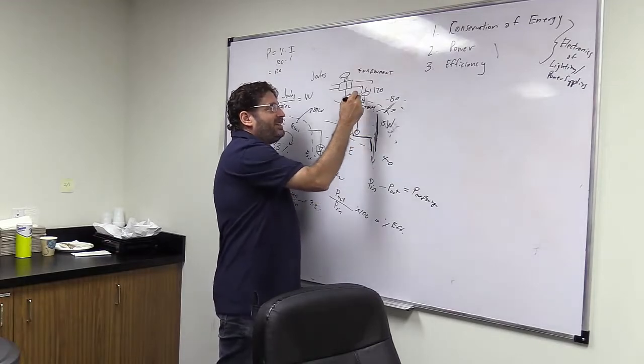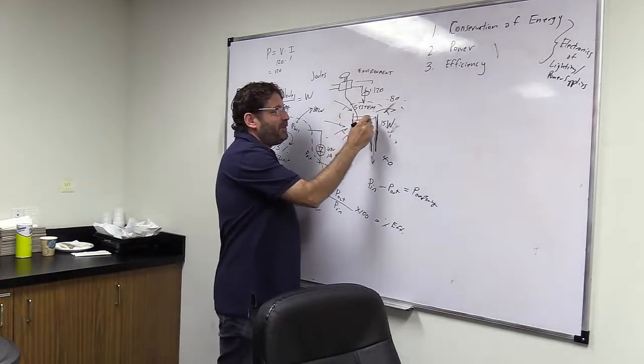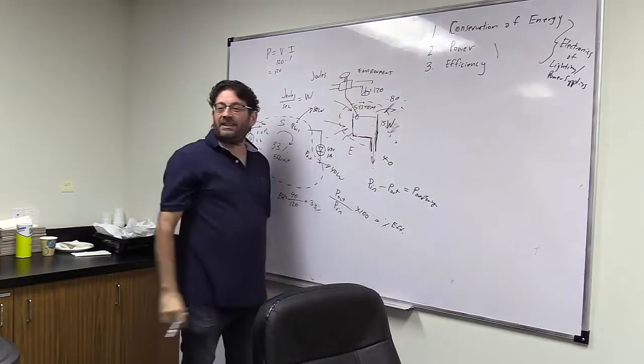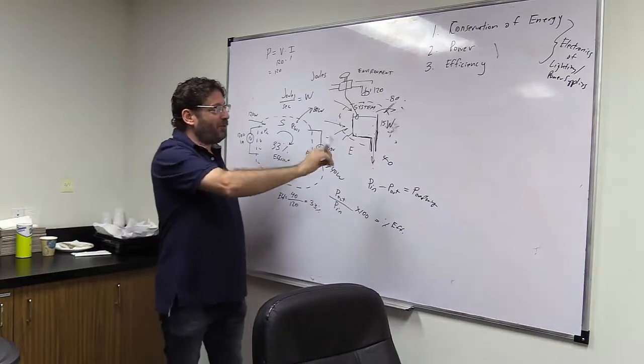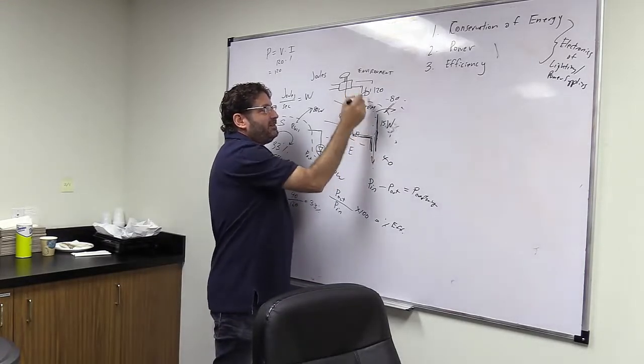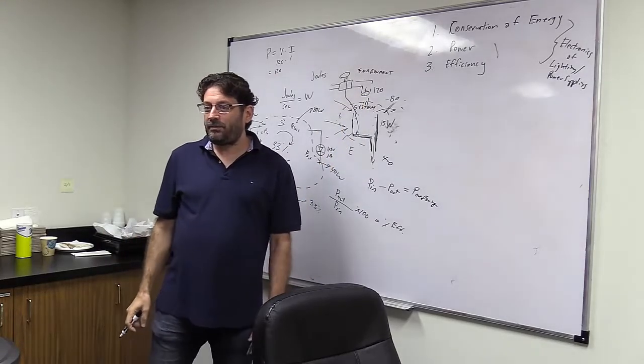The way it works is that it fills up the tank until it gets to near the top where the float is here, and then it shuts off the valve, right? And it stops. And then when you flush the tank, it goes down to the bottom, and that's where the valve starts to open again and water pours back in. It goes through this cycle, okay?